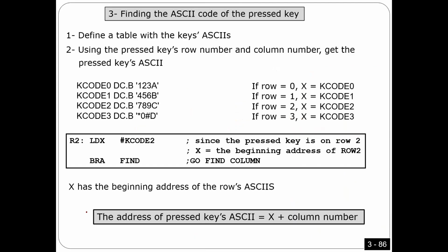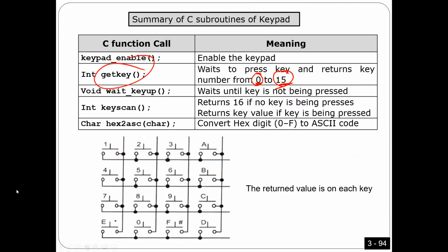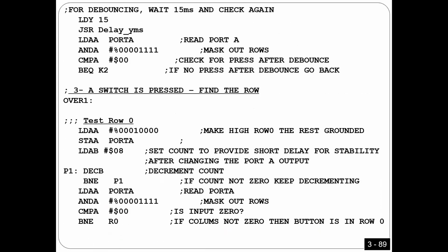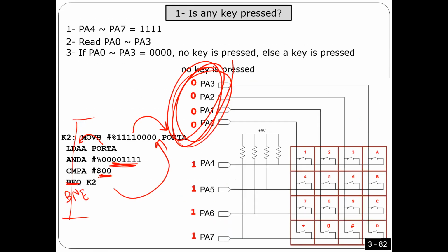This will be something equivalent to key up, in equivalent to this C function, the equivalent one if you want to do the same thing in assembly. Very easy. All you have to do again, guys, number one, I'm going to output 1 1 1 1, right? And then I'm going to keep looping until I find 0 0 0 here, because 0 0 means you released the button.